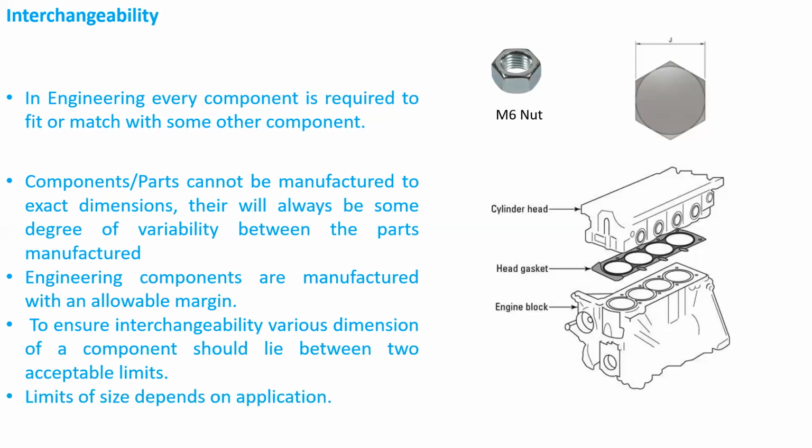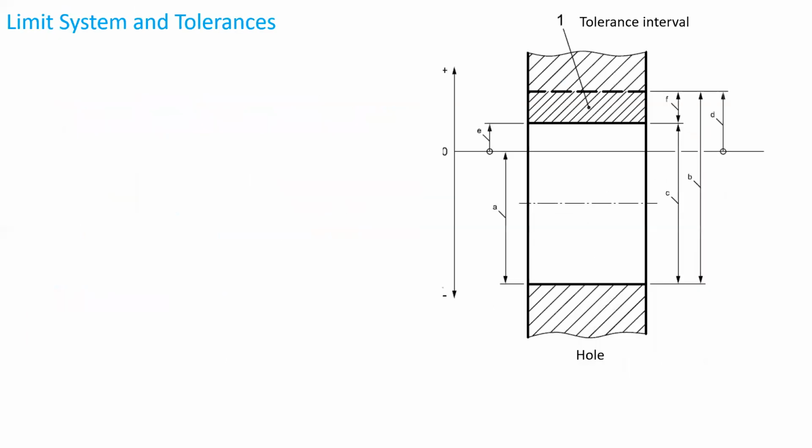And the limits of size depend on application. The closer the limit of size, higher will be the manufacturing cost. Now, based on the concept of interchangeability, the limit system and tolerances were introduced.